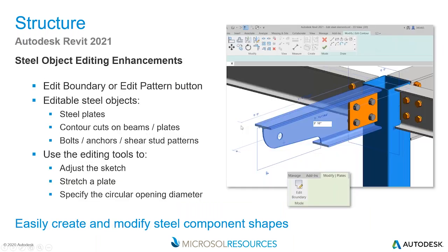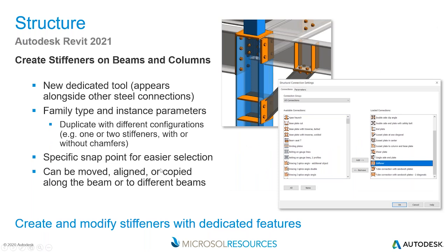What else? Total custom cuts and contours. So as you get more and more details onto the steel and the connections, you have the ability to control more flexibility when detailing. Okay. So I'm speeding up even more. So I love the ability to populate connections by just selecting columns and grids. So now, more enhancements with stiffeners and the flexibility of coming in and controlling how this is going to be copied along all the different intersections of beams and columns.